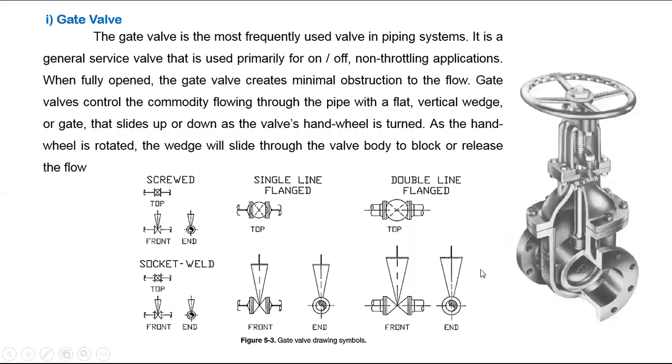And also you have to think about the valve operation height. Normally our average movement height will be 2 meter only. So averagely we give valve operating height 1.6 meter, maximum 1.6. Normally we give 1.2 to 1.6 only. For the worst case only we give 1.6. So normally operating height 1.2 is the feasible height. So you have to think about the feasible height of the valve operation also.